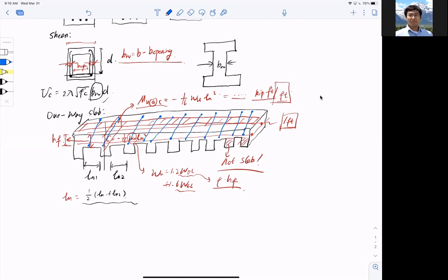Last but not least, when you design for either flexure, which means the longitudinal reinforcement, or the transverse reinforcement, you have to make sure that you find the spacing. That is what you're designing for, spacing. Per the ACI code, there's a conversion on how to convert the provided reinforcement to the reinforcement per foot. Remember that equation? Go back, dig it out, and familiarize yourself with it.